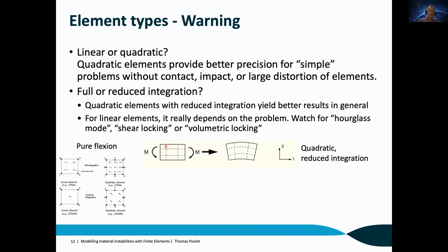And you can see that they are crossing at 90 degrees, which is what we start from. And when we flex it, those lines remain at 90 degrees because the top and bottom can bend. And this is good because this 90-degree angle translates into not having any artificial sigma 1-2 shear stress, basically.